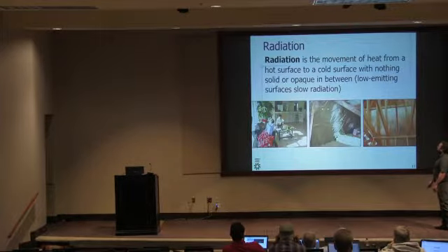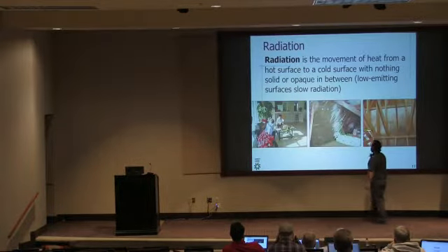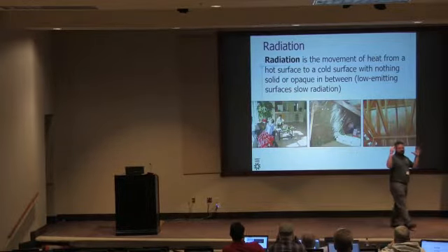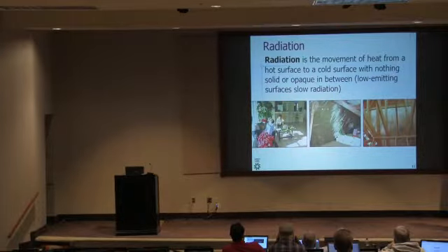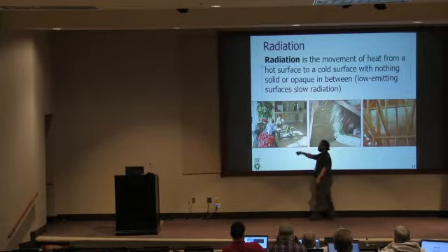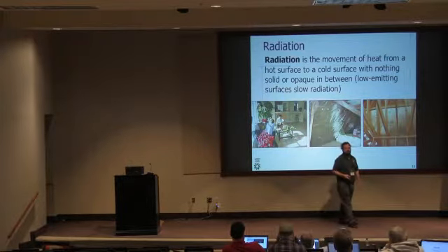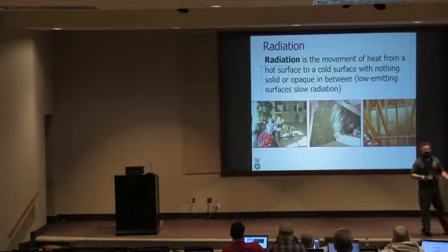All right. Radiation. Our homes really experience radiation primarily in two places: our attics and our windows. And again, that's surface to surface. So the sun, big, hot, glowing ball of gas in the sky, looks down, sees the earth, warms the earth, looks down, sees our roofs, heats up our roofs, looks down, sees into our windows, sees interior surfaces, warms up the interior surfaces of our house. That becomes load that we have to reject with our HVAC system, right?